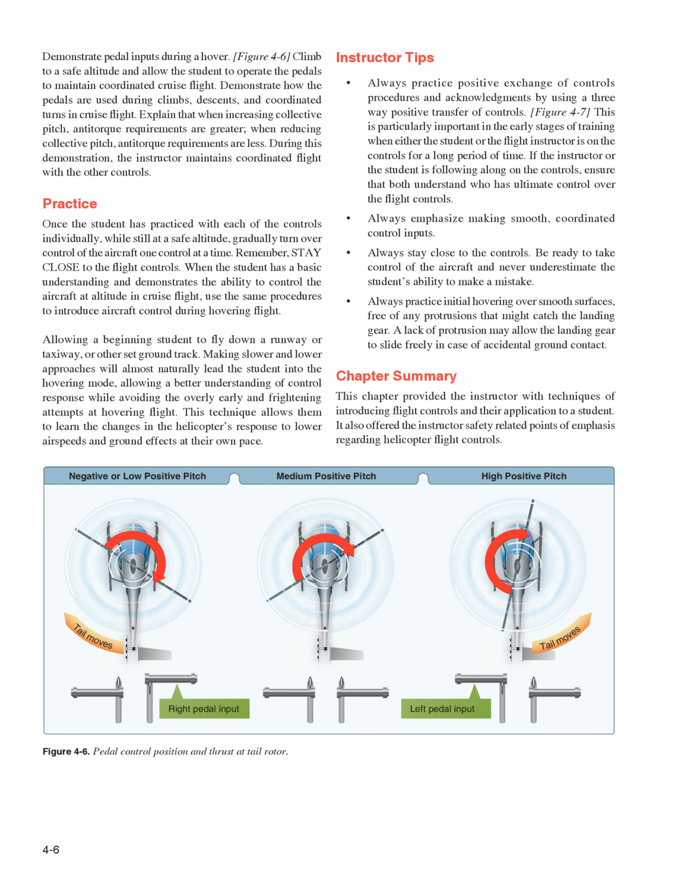If the instructor or the student is following along on the controls, ensure that both understand who has ultimate control over the flight controls. Always emphasize making smooth, coordinated control inputs. Always stay close to the controls. Be ready to take control of the aircraft and never underestimate the student's ability to make a mistake.